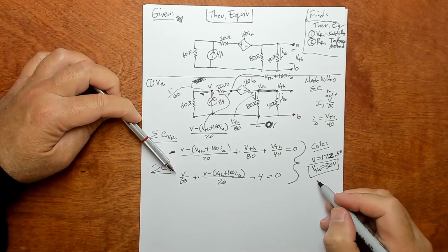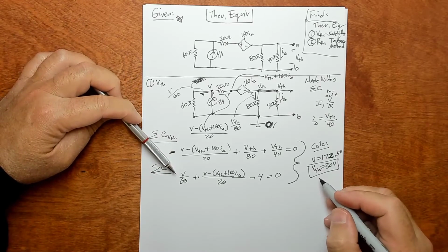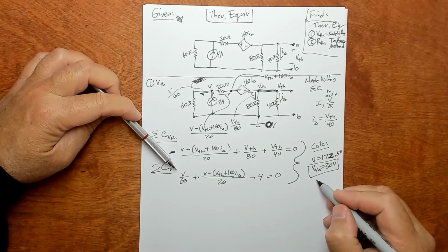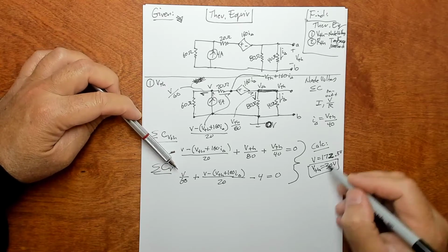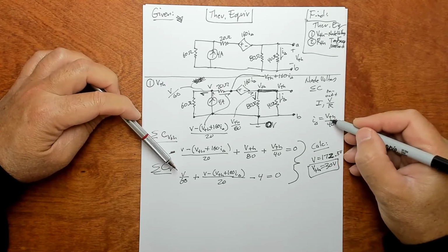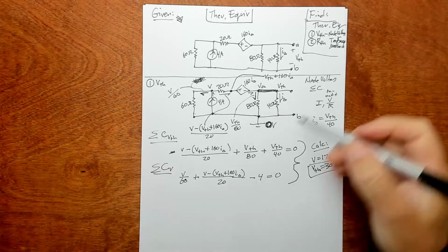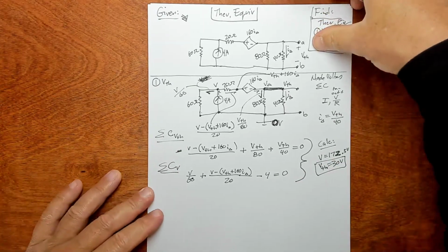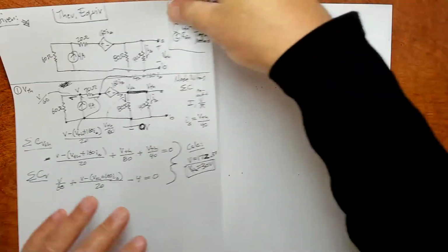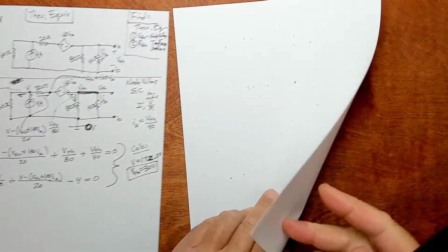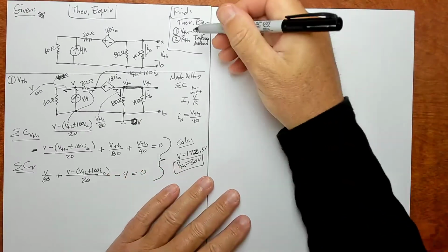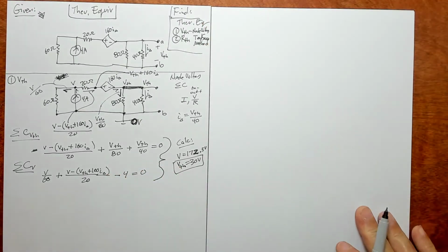Well, that's all we care about. I mean, I delta would come out of this too. You could get I delta if you knew V Thevenin. Anyway, all we really care about is V Thevenin, and we got it. So that's the step 1, or process 1. It's much more than a step, I guess. Let's do process 2, R Thevenin via the test source method.